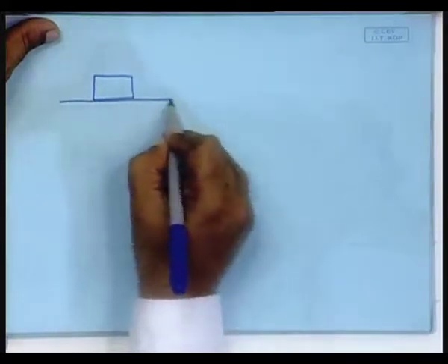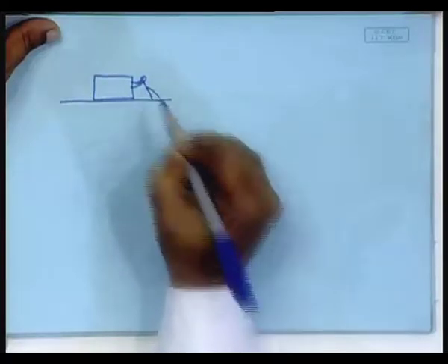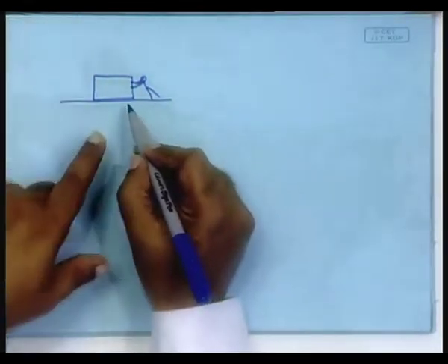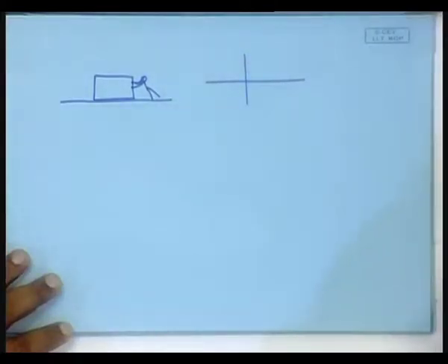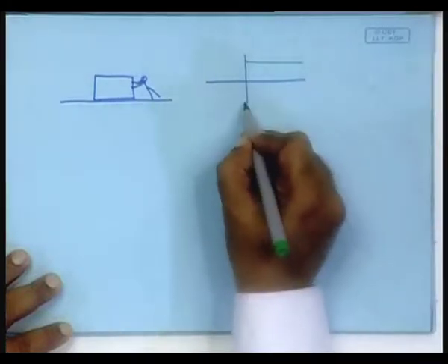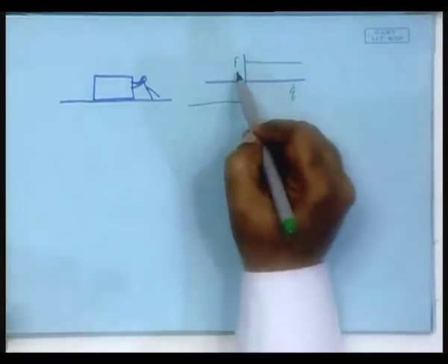So, where you have got a body resting on a dry surface, and if somebody pushes it, then initially it will not move, and then when that threshold force is exceeded, it starts to move, and then after that the force due to friction remains more or less constant. So, that is the character, and we have already seen that it can be represented by means of a graph something like this, q dot here and a force here, okay, force due to the friction I am talking about.